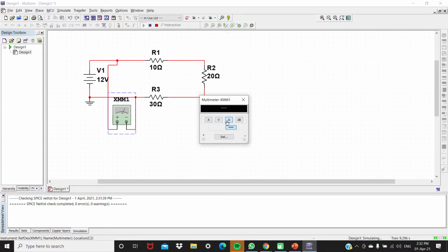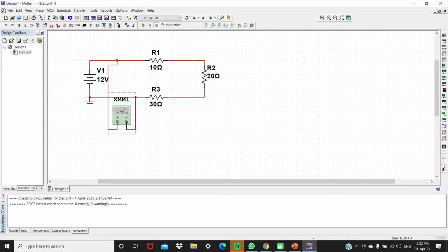These are the things that we need to explore when we use software. Being an electrical engineer myself, we shouldn't get 1.2 giga ohms. When we get 1.2 giga ohms, it seems that there is somewhere in the circuit where it is actually not connected.